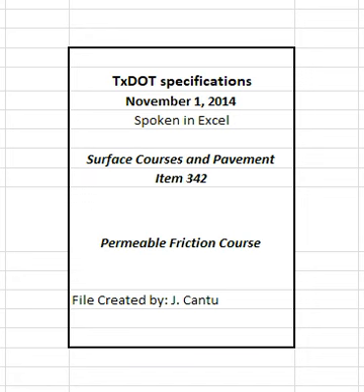Table 4. Master gradation limits, percent passing by weight or volume, and laboratory mixture design properties. See table in specifications. 1. Defined as maximum sieve size. No tolerance allowed. 2. Mold test specimens at the design and optimum asphalt binder content, JMF1. Perform the test for informational purposes only when no minimum number is specified. 3. May be decreased when approved.